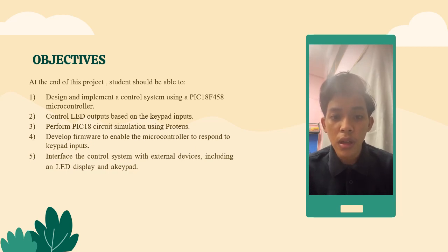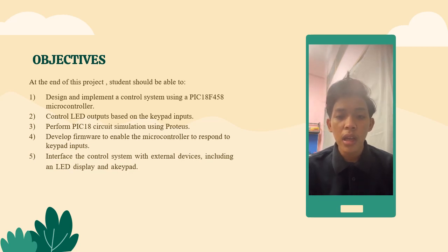Third, configure the keypad as an input device for user interaction with the system. And fourth, develop firmware code to detect keypad inputs. And finally, initialize and configure the microcontroller peripherals to effectively interface with the keypad and 7-segment display.